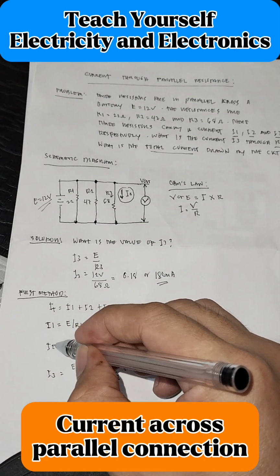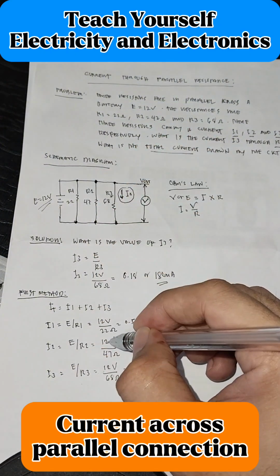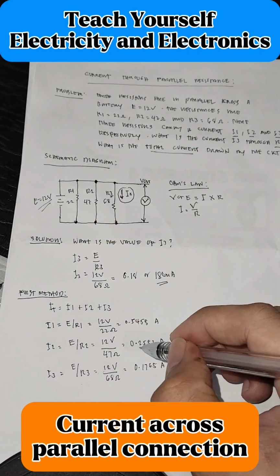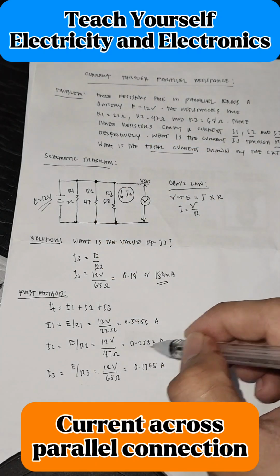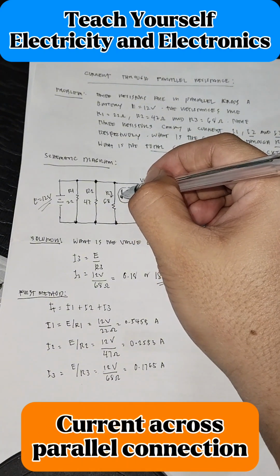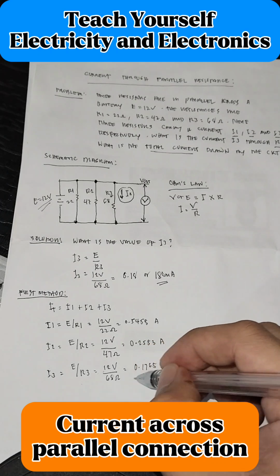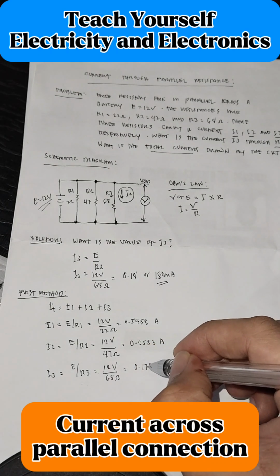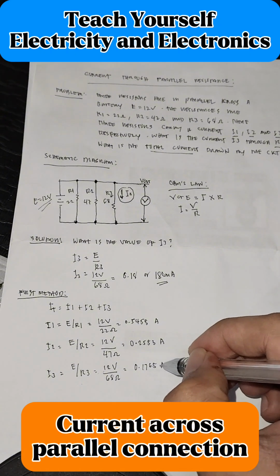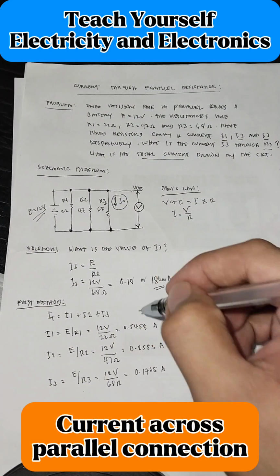For current 2, 12 volts supply and 47 ohms load resistance, which is 0.2553 ampere. For current 3, 12 volts over 68 ohms, which is 0.1765 ampere. I just rounded this off.